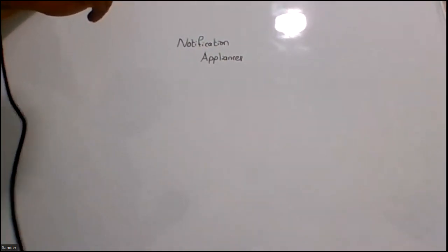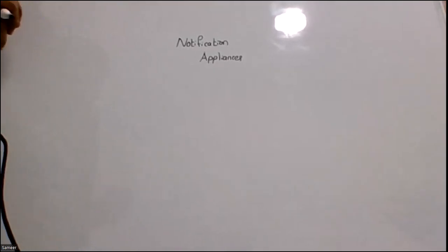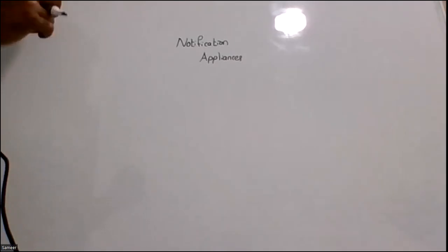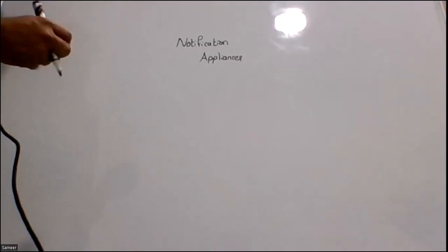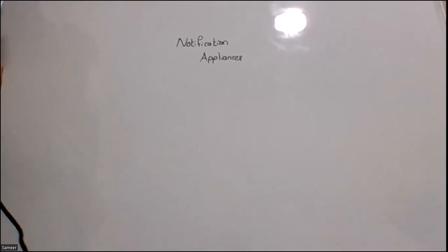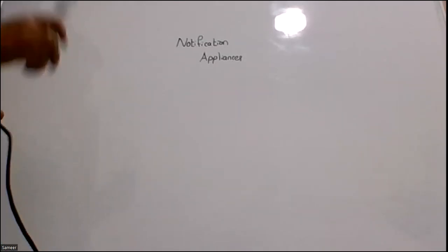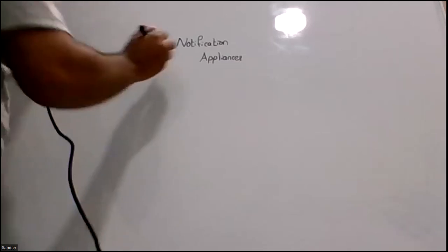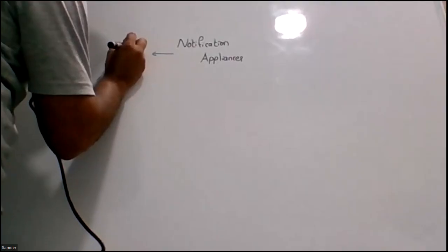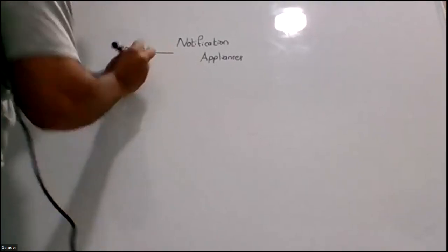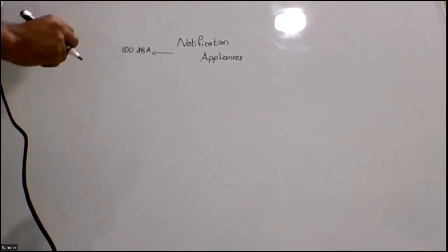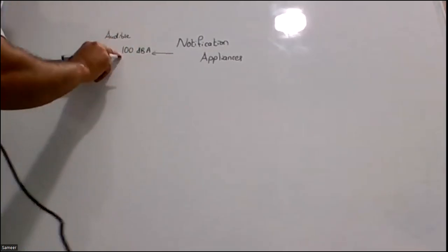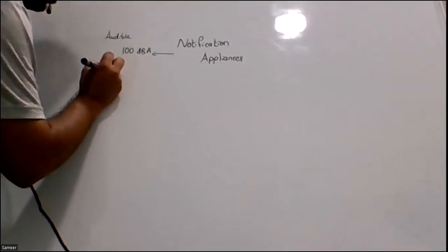If you remember, last time I discussed that the permissible value for the notification appliance is 75 dBA. That is enough for a residential occupancy to make occupants aware of any type of hazard. This value can go up to 100 dBA if the person is on sleeping pills or has a hearing impairment. Whenever an audible notification reaches 100 dB or above, a visual notification is necessary.